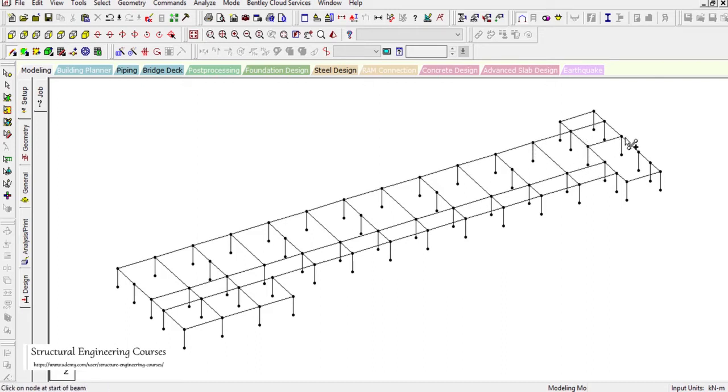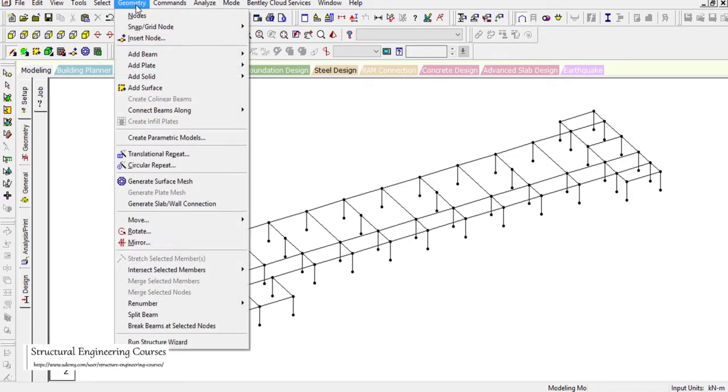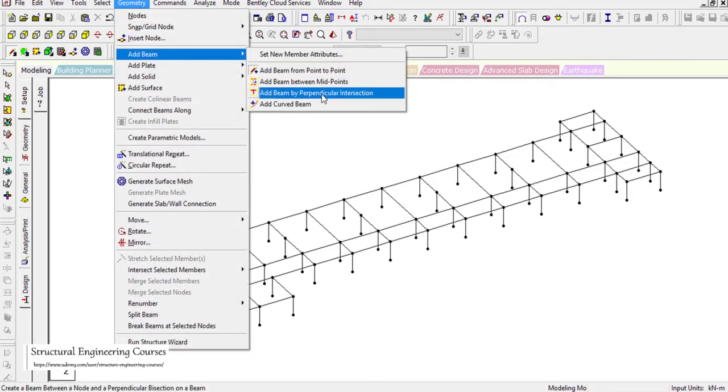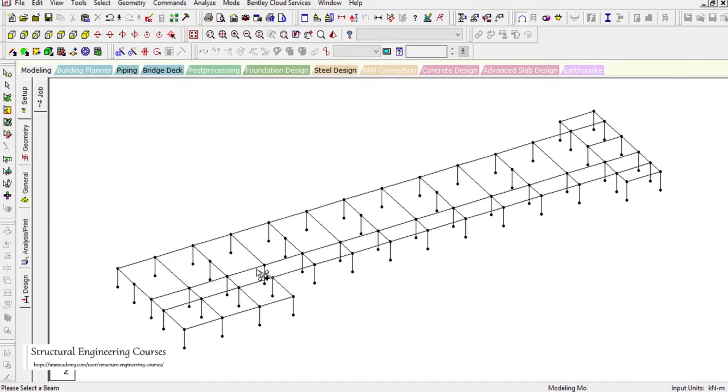And we can make the beams here also. See, a good structural engineer will always tie the columns as much as possible, because he knows that the more we tie the structure, the more economical and integrated it will be at the time of an earthquake.